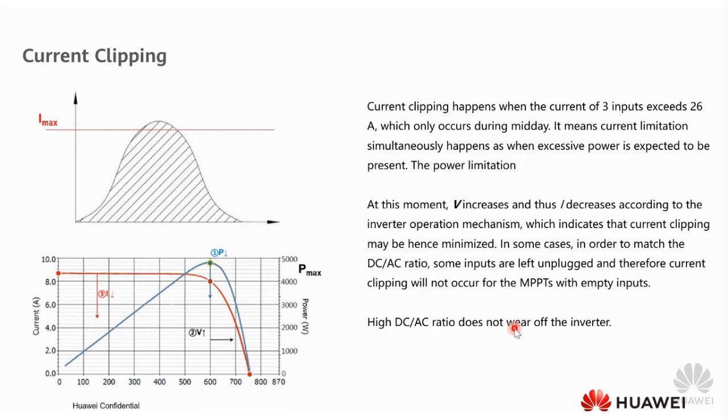But imagine you have, for example, approximately 2,500 hours of sun around the Mediterranean Sea area, and you place an inverter there. But if somebody buys the same inverter and places it in Northern Africa or in the Sahara, where the hours when the sun is shining are so much higher, it will actually have the same effect on the inverter that the DC-AC ratio is changed.